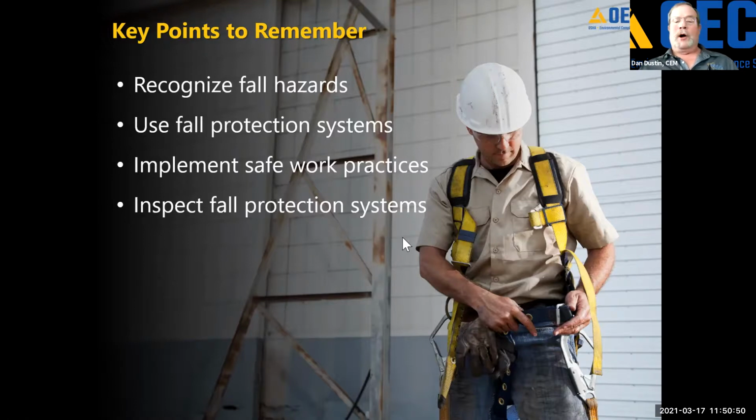Regularly inspect the fall protection systems. This is something that we run into all the time on stick-built construction, where fall protection such as guardrails in stairwells have been taken down because the drywaller or the painter had to get in behind them and they were never put back up. Or window openings or door openings to an outside wall have been unguarded because they had to get something through the opening. So a regular inspection of the fall protection systems in place is very important.